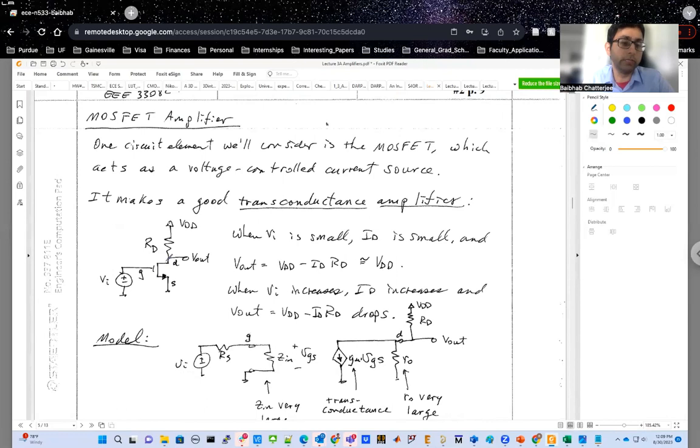That very simple implementation could be something that will be called a MOSFET. We'll be discussing MOSFETs in our later lectures in detail. But for now, you can just assume that what this MOSFET does is that it converts the input voltage to an output current. That's the job of a MOSFET. The MOSFET, or metal oxide semiconductor based field effect transistor, converts the input voltage to output current.